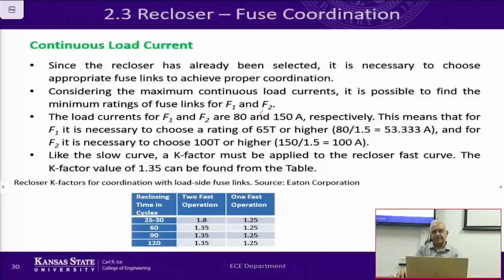No, it's not that. Let me. Okay, we chose 65T and 80T because the load is specified to be 80 amps and 150 amps. So you have to pick a fuse to allow 80 amps of current to flow on the line.